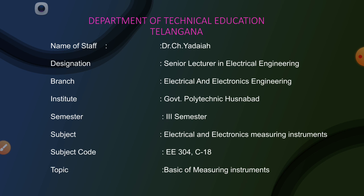Whereas in liquid friction damping, high viscosity, non-corrosive oil is used. But once oil is used, there is a possibility of it creeping out. So the quantity of the oil may reduce, and then the effect may change. It is more efficient, but it can be used only in the vertical position in the case of liquid friction damping, fluid friction damping.